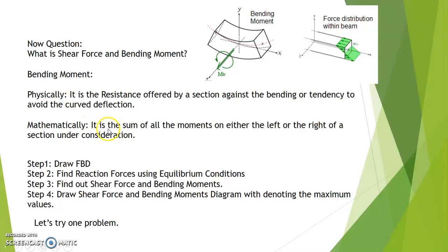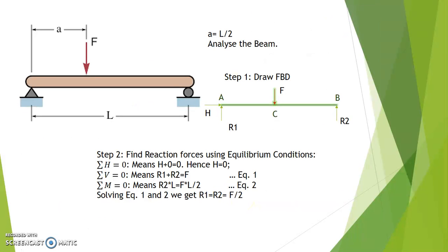Mathematically, we can say that it is the sum of all the moments on either the left or right of the section under consideration. As I have already told you, I have jotted it down in 4 steps. First draw a free body diagram, then find the reactions, then the shear force and bending moments, and then draw the shear force and bending moment diagrams.